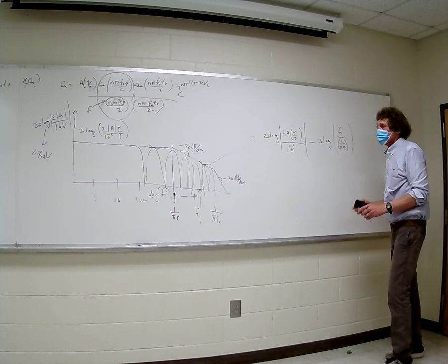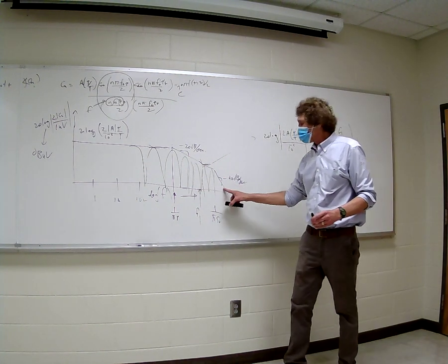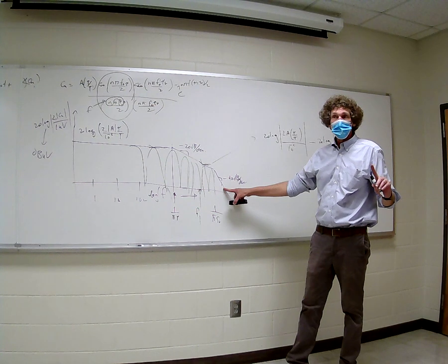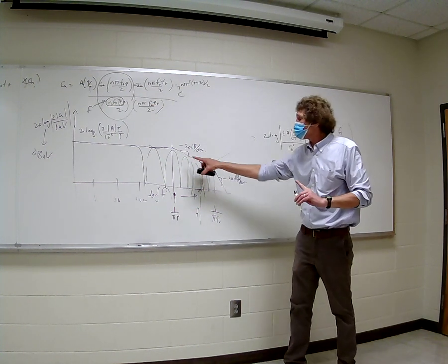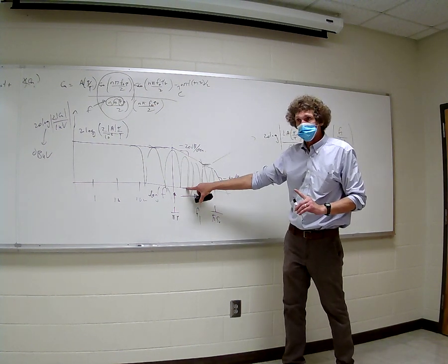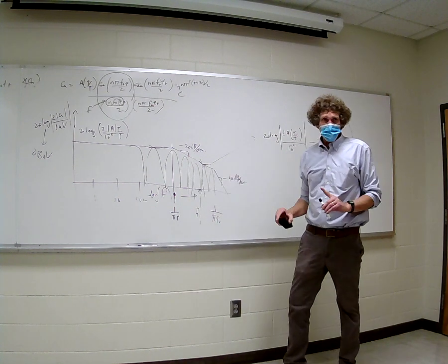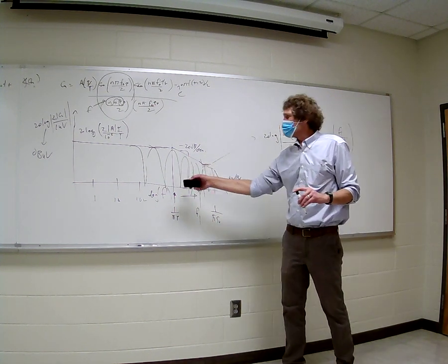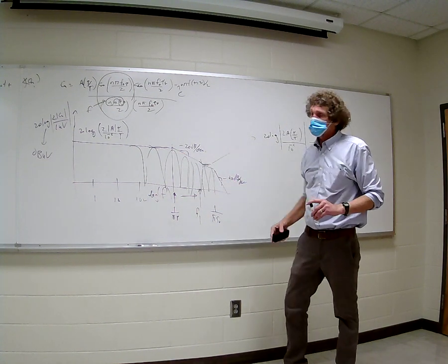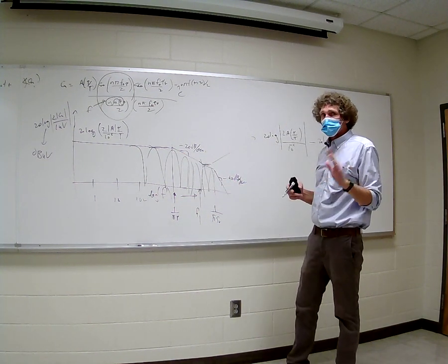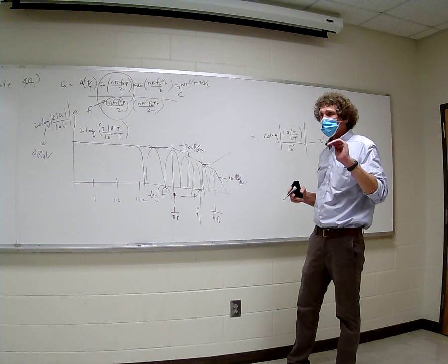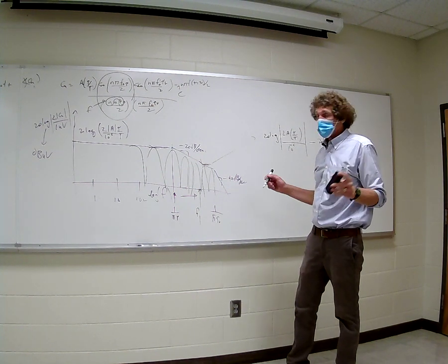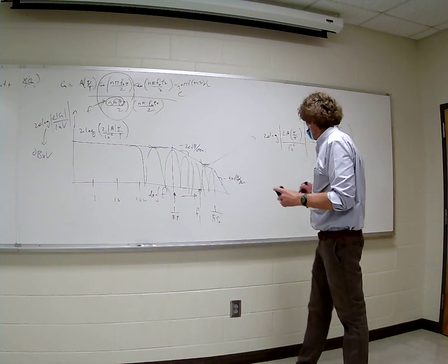All right, now, what happens if it's not here, though? What if it's out here? Y'all follow me? And we're worried about the worst case. In actuality, it might be 0 if we're at a relative null. You follow me? But don't worry about that. What you really want to worry about is, because these are actually going to be discrete lines, this is the envelope of the sinc functions. What you're always worried about is the maximum possible value, because that's the one you always work against, even if it doesn't occur.